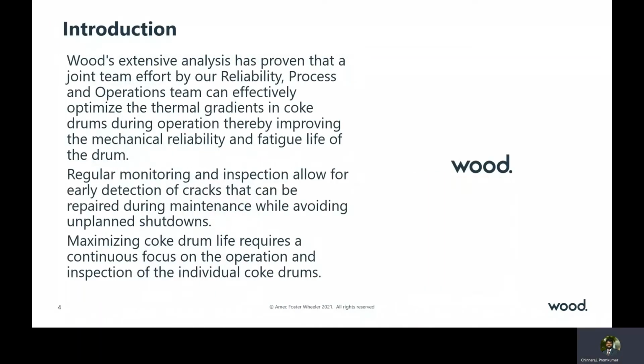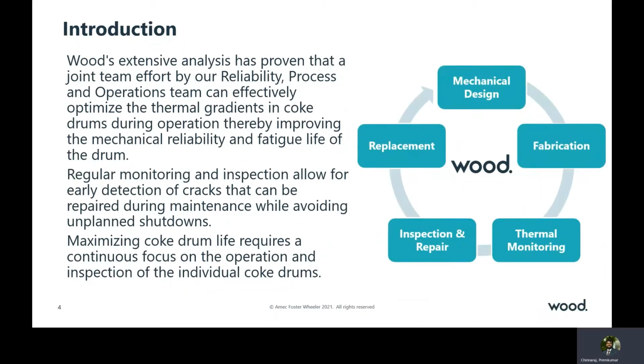At Wood, our goal is to design fatigue-resistant coke drums that meet a minimum of 7,000 life cycles. We also coordinate with our fabricators to make sure they meet our stringent requirements provided in our specification to achieve the intended fatigue life. After startup, we assist field in regular monitoring of thermal data to optimize the operational parameters, thereby increasing the life of the drum.